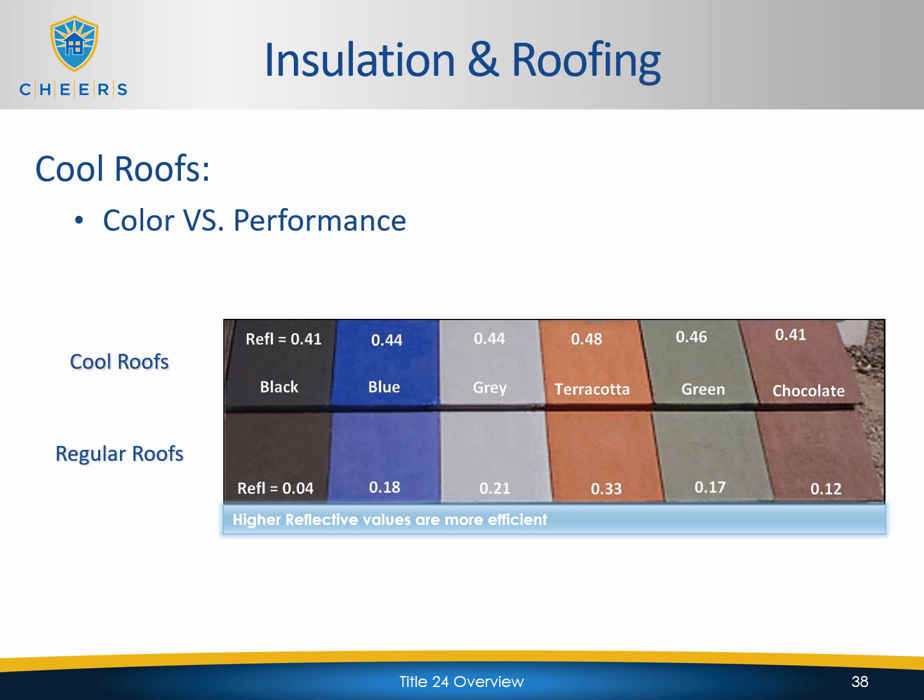Now this particular slide is really just here to show you the difference between a regular roof and a cool roof, and the fact that having a cool roof doesn't mean that you're limited to the colors of tile or product that you're going to be installing. So basically, by looking at the colors, you would think the darker colors would be worse off, and they are, but nonetheless, you could still have a cool roof that is black in color.